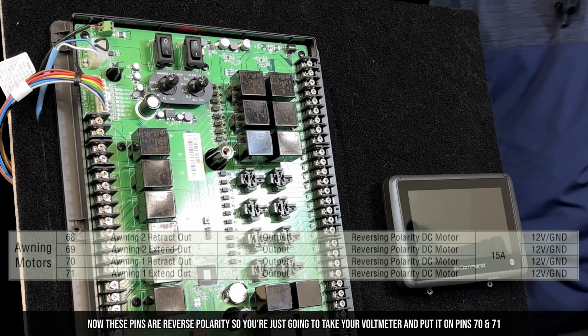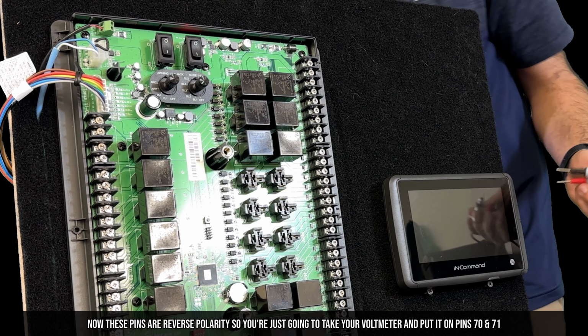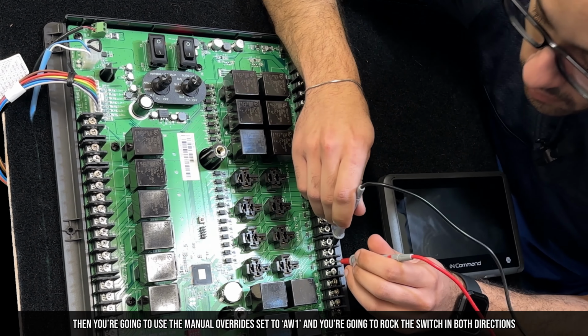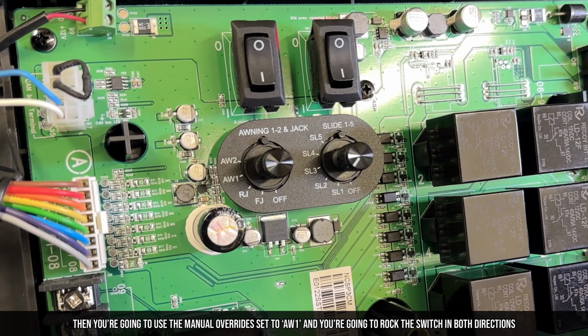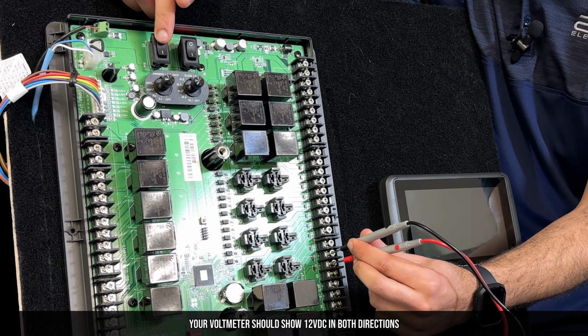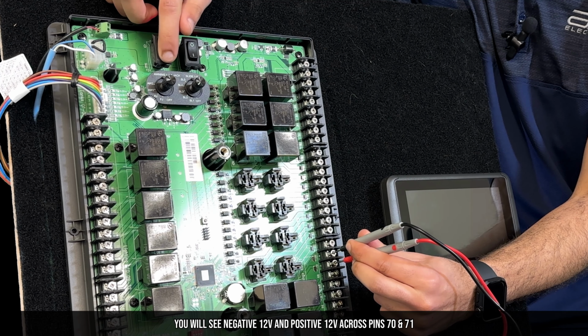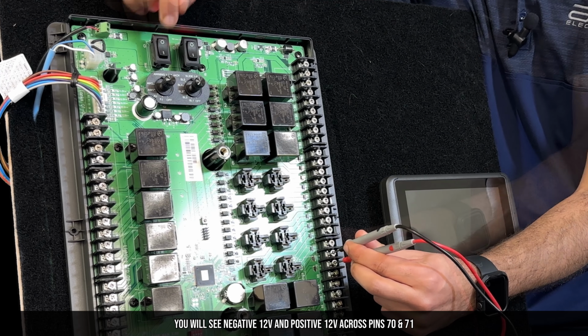Now these pins are reverse polarity, so you're just going to take your voltmeter and put it on 70 and 71. And then you're going to use the manual override set to awning number 1, and you're going to rock the switch both directions, and your voltmeter should show 12 volts in both directions. You will see negative 12 volts and positive 12 volts.